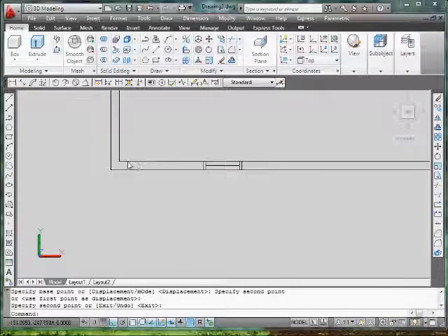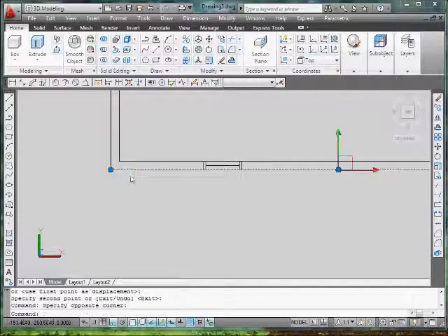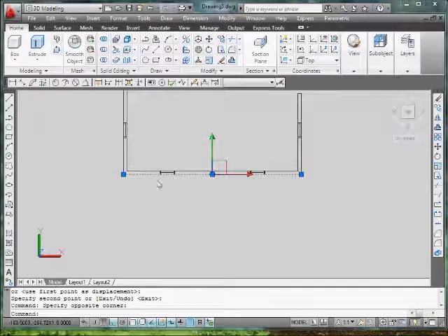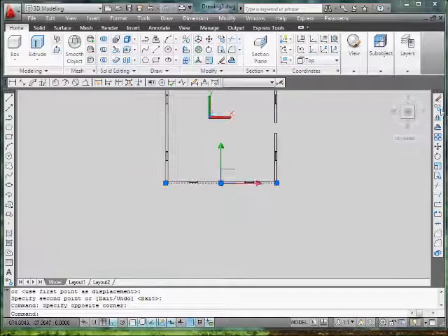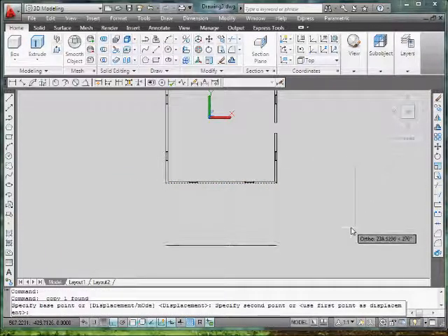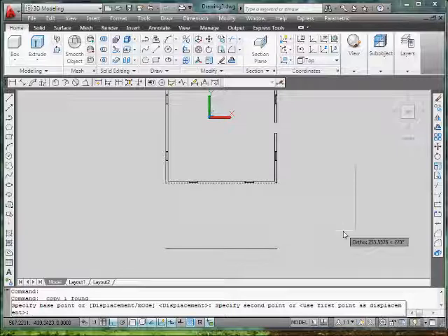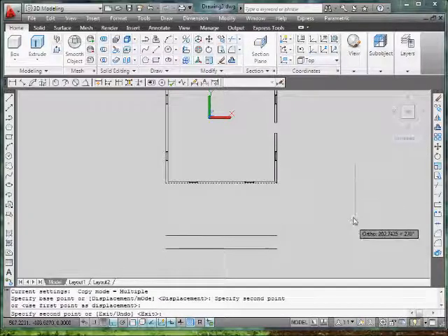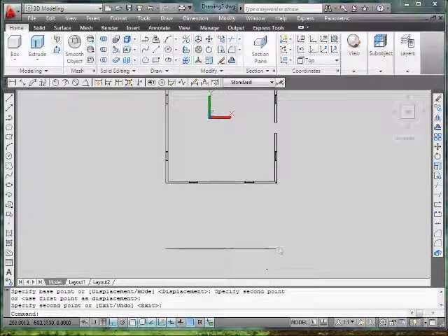the top one, because that's actually shorter than the overall length of the house. So do select the bottom line, go to the copy command, and we're going to copy it down, I'll say about there. So I did 250 inches or something. That's fine. We have that line, that's going to be our base of the front view.